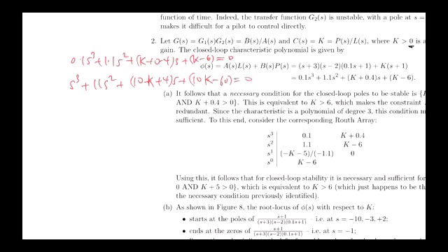Now, in order for two of those roots to be on top of each other on the real axis, this must have the following form. It must look like (s + a) squared, because that will put two roots at minus a. But we've got a cubic, and so we need an (s + b). So in order for this to have two roots at s equals minus a, k must assume a value that makes this look like this. So how can we do that?